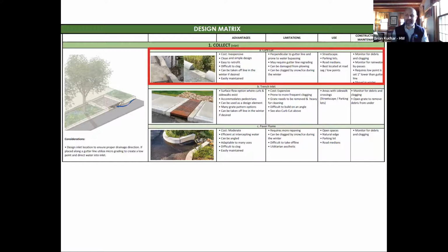That's great. I just want to add, to keep in mind when we're designing this and we go to the install, we really need to make sure that the water is going to get into the practice. And sometimes that 90-degree turn is a little tough. So we'd like to try to lower the grade a little bit in the road, so it really forces that water in. I'm assuming you're okay if we have to do a little work out in the pavement. Yeah, we did a recent patch, and we actually pushed everything towards the curb because it was icing up across the street.